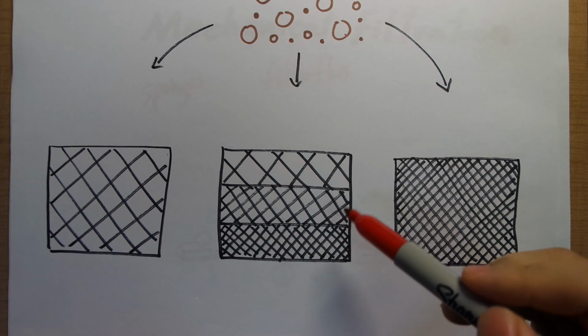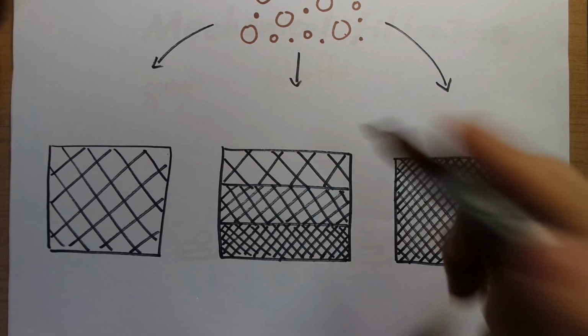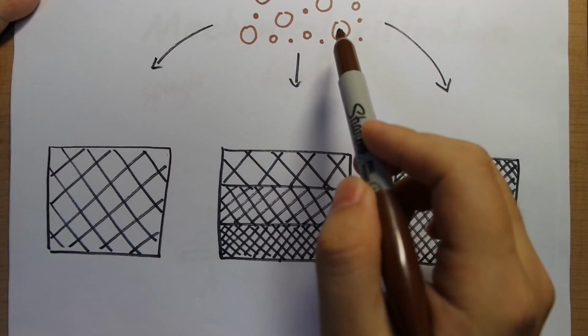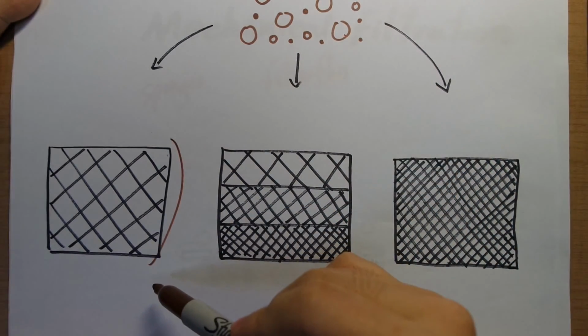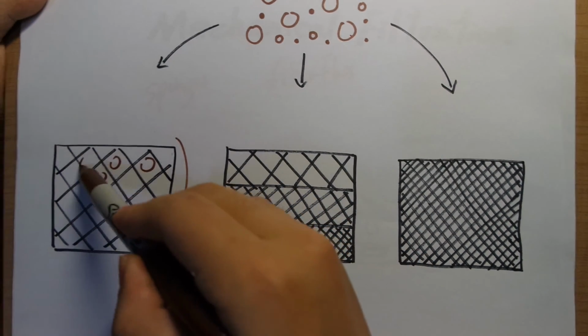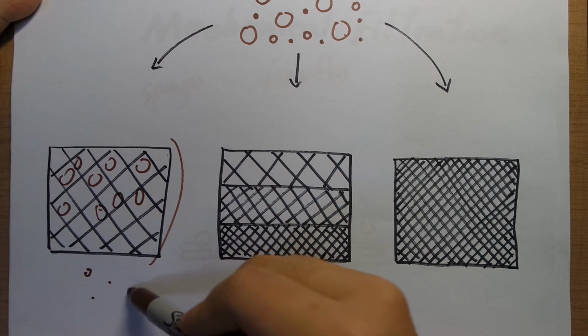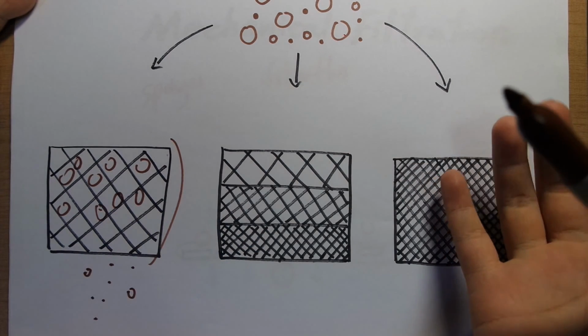And I see a lot of people confuse this. The reason you want to do this is, let's say you have this water with a bunch of mixed particles and you only have coarse filtration. Now this wouldn't work very well because the coarse particles will get stuck in your mechanical filtration, but all the medium and small will get through. Now that's pretty obvious, right?